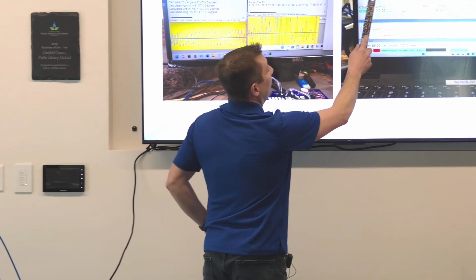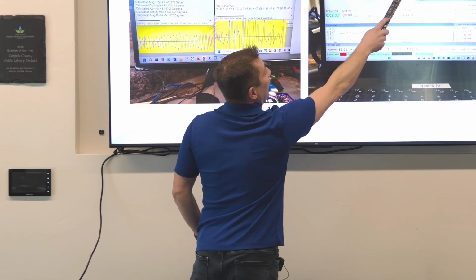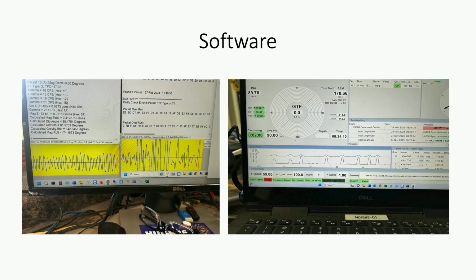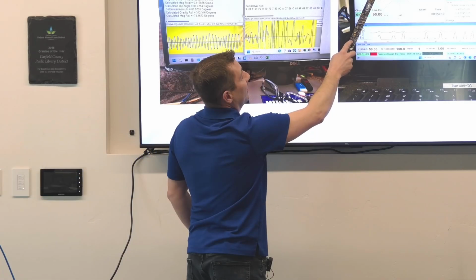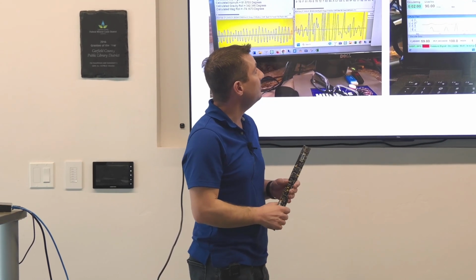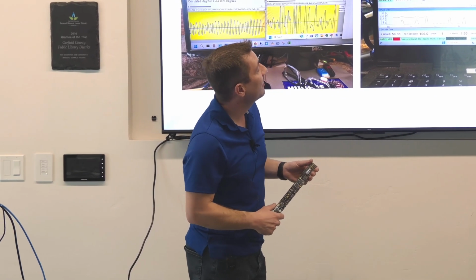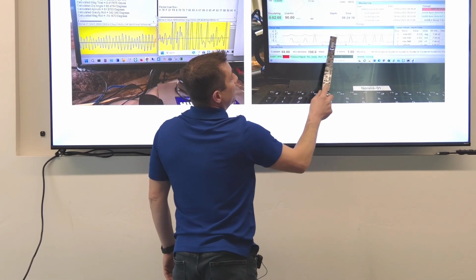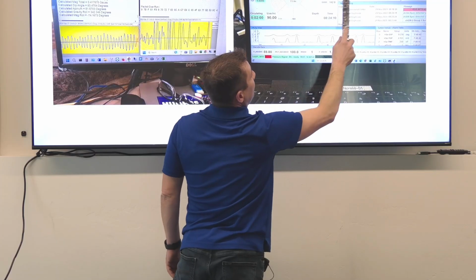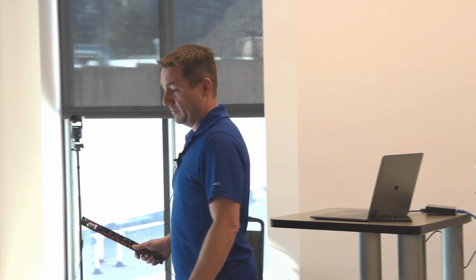So when we go to take a survey, we have our inclination, our azimuth, our temperature, our current gamma, the time, our live inclination, which is from that number over here, our magnetics at that point in the ground, our dip angle to the earth, our gravity, the G's, and how long we've been circulating. That gives you a display of the signal itself. Based on the quality of the signal, it'll bring up qualifiers and start listing them out here, and it'll tell us if our survey is good or bad. A lot of times when we go to take a survey, some of the fluid is still moving down at the bottom of the well, and the survey won't be good.